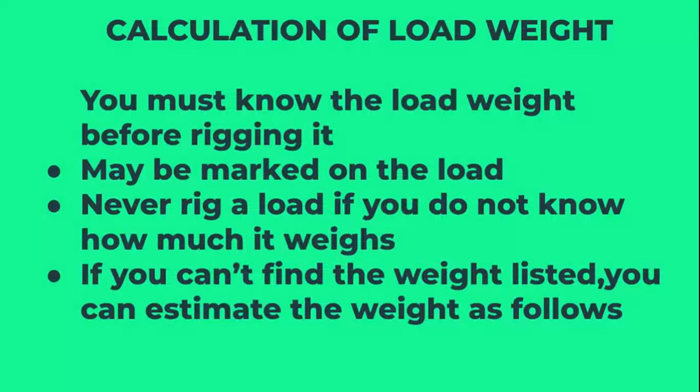So, calculation of load weight. You must know the load weight before rigging it. Any job you perform to lift or lower, you must know the load weight, how much it is. If you don't know the load weight, as I already explained in the previous slides, just go through the calculations or use a load cell to measure the weight. It may be marked on the load.